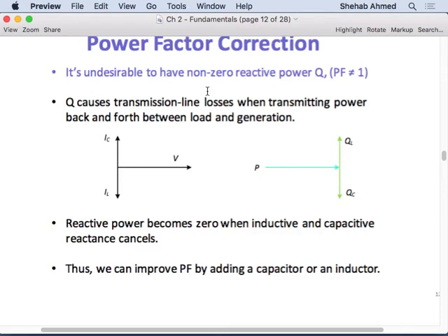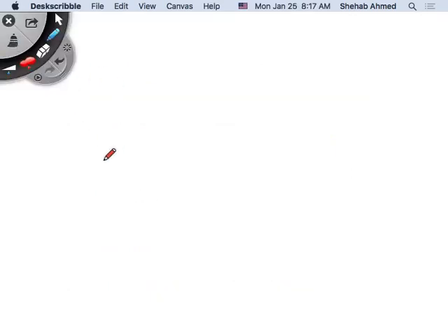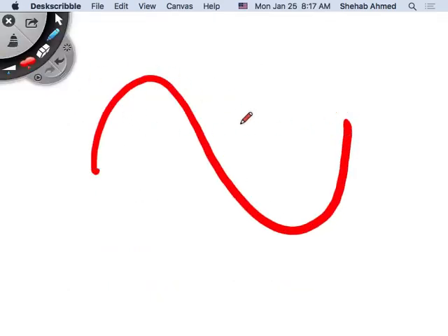So that's one problem. The other problem is, if you have an AC current and then you add a small inrush, so you have a sine wave and then a nice peaky transient, that is going to cause harmonics, right? You have a nice sine wave, but because of the inrush current, as soon as you plug in the capacitor, something like this happens. So you no longer have a nice sine wave anymore. These harmonics also affect equipment negatively, right?